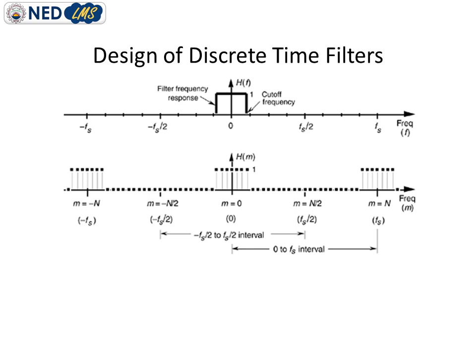So basically this discrete representation of the ideal low pass filter is the periodic response as shown in the second figure. Both are the same. The first one is the continuous frequency response and the second one is the discrete frequency response, but due to discretization that response becomes periodic.